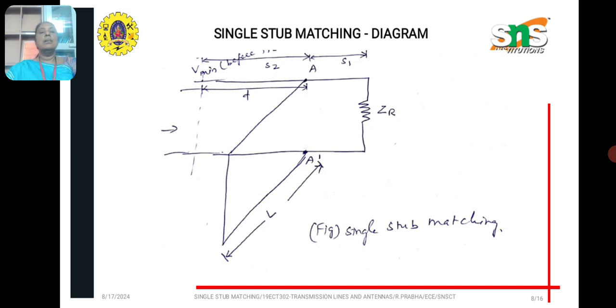A stub of length L is shunted across the transmission line at a distance S1 from the load, and the point is denoted as A. From the point of stub connection to the first V minimum from the load, the distance is S2, and this distance is D.